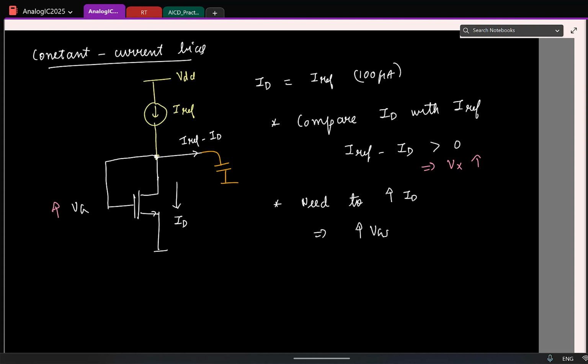So now if you think from the first class, we wanted to make an op amp with an infinitely large gain. Why did we want to make something with an infinitely large gain? Yeah, but where will I use such infinite gain systems? Negative feedback. So I started with the goal of making an op amp to be used in negative feedback, and it seems like to make an amplifier and to bias it properly, I again rely on negative feedback, right? So that's the beauty of this. That is nature leading its way to achieve your goal.